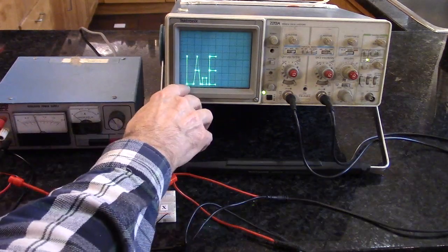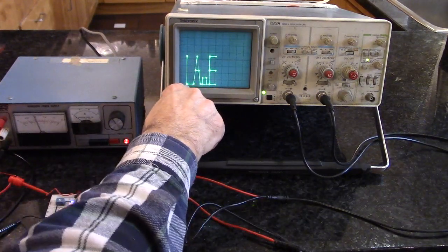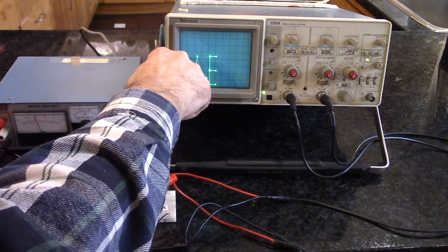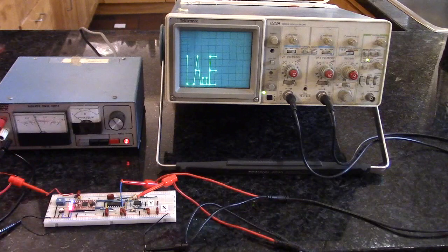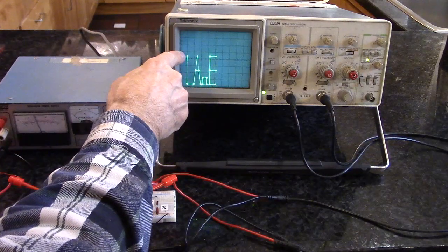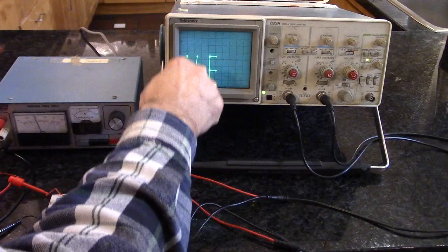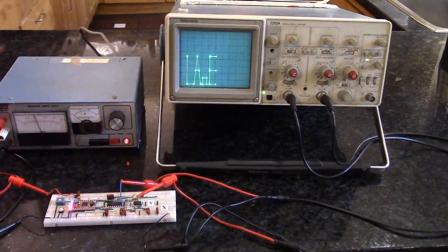So we start out putting out 0, 0 volts. I've got that sort of in the lower left-hand corner. And then we output the maximum voltage at this point. So the DAC that we're using puts out 2.048 volts. It's maximum voltage. So we don't change the X, but we change the Y. And then we change the Y back to 0. We go over, and that's why we have a set of connected dots.